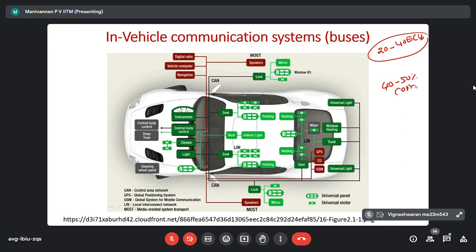Correct? You can say I want a carburetor, but if you put a carburetor, you cannot sell the vehicle. You cannot meet the Bharat 6 standard with a mechanical system, without the fuel injector, where you can control fuel quantity in milligrams, whenever you want. Already we saw the fuel injector, CRDI, GDI. Without that, you will not meet Bharat 6, CARB 6, or Euro 6 standards. The vehicle cannot come out of your factory gate without the Bharat 6 standard. You can't drive it on the road, except maybe you can test inside your factory only. You make 1 million cars, inside your factory only you can drive. You cannot sell it worldwide. So mechanical-only things are not possible.